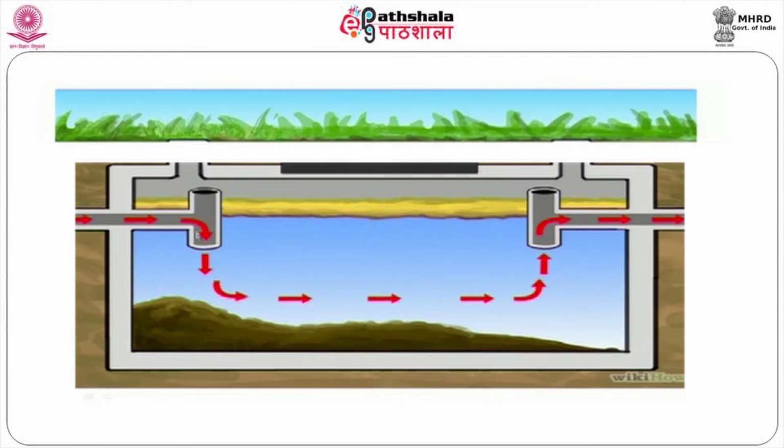In order to avoid turbulence while admitting wastewater into the reactor, we have to provide a T type entry pipe. The pipe is elevated, and the purpose is to avoid entry of scum particles. So, this is the configuration here. Here the clarified effluent can be collected from the reactor by providing a T type outlet pipe at the outlet. Here is the floating matter, the scum that is generated during anaerobic activity.